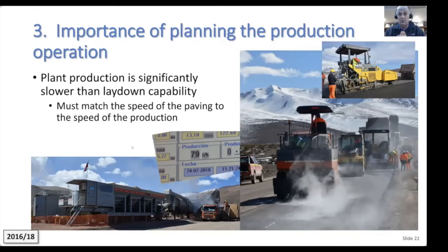And there's your end of truck. It's a thermal segregation in effect. You get this material which is cold, and then they get the next truck and they pave that one and stop again, have another cup of tea, and so on. But you end up with this patchwork quilt as you're going on.